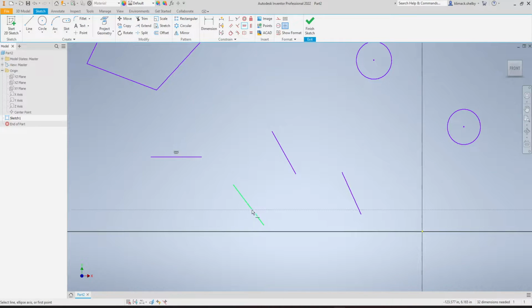Let's do that one more time. With this line down here, one more thing before I click on it: when I hover my mouse over this line, it gives us a dotted line that runs across the screen left to right. It's showing me that if I click on this line, this is the direction it's going to be running, along this dotted line, this little preview that's popping up. So I'm going to left click on it. And sure enough, it runs along that dotted line, left to right. So that's the horizontal constraint.